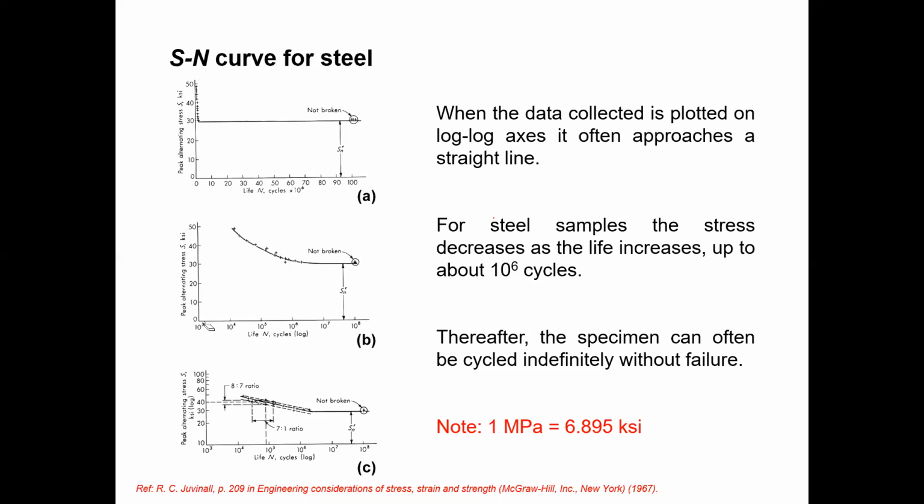But you can see here a very important thing. They only consider 10 to the power 3. So you need to keep it in mind. Until 10 to the power 3 cycles, there is no significant variation of the strength. Little bit drops are there, but that drop is not significant. So you will consider the initial point of this curve as 10 to the power 3 cycles. So you need to keep that in mind.